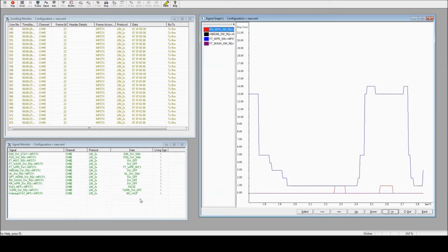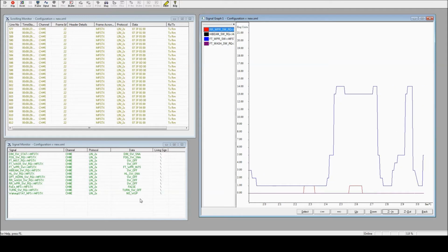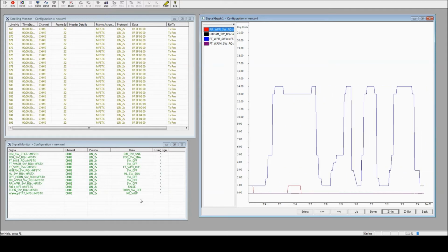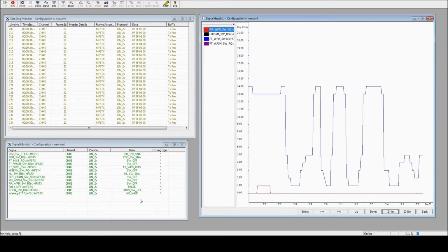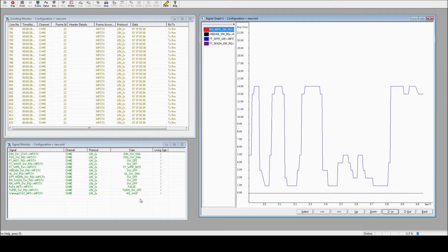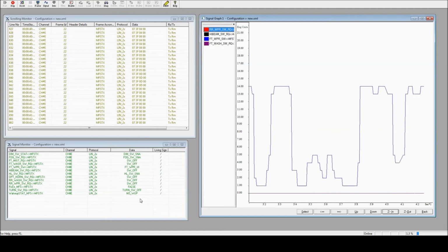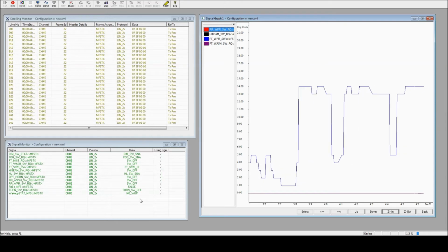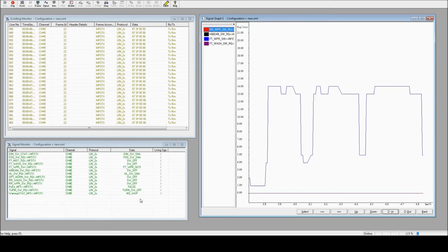And so we've achieved our goal of using Hercules with the Gryphon to emulate a LIN bus using an in-vehicle LDF file. To review, we started by verifying our connections and our slave using GryphRx and GryphTX. We then configured Hercules and ran the emulation. You can save your configuration in Hercules so that you can use the same configuration next time.